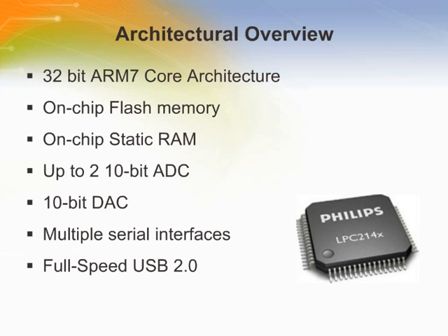The LPC214x series is the only ARM7 microcontroller family with full USB 2.0 compliance and USB.org certification as of 2008. The full-speed USB 2.0 device supports 32 endpoints with 2 kilobytes of endpoint RAM, 8 kilobytes of RAM usable by the USB DMA, and all data transfer modes. These MCUs allow designers to add USB functionality to almost any end application.